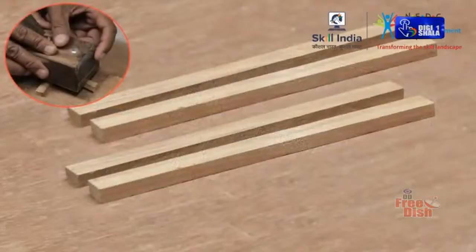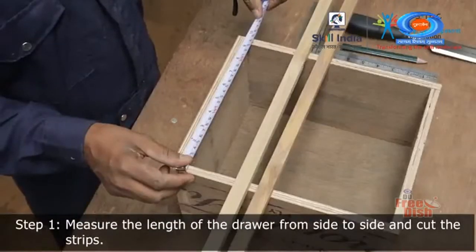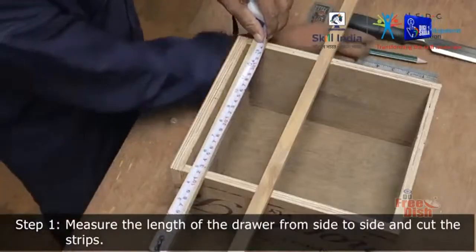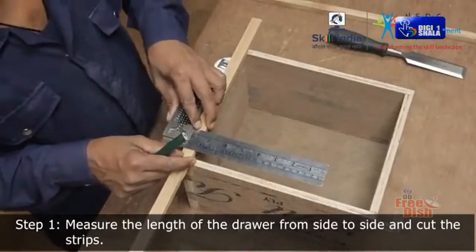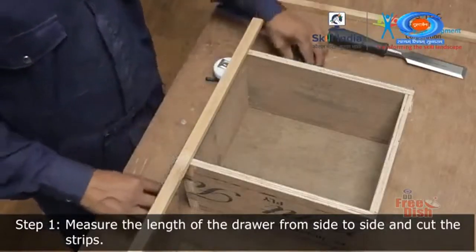Before you start, ensure the back side of your beading is smooth and even. If it is slightly uneven, use a smoothing plane to smoothen it. Using a measuring tape, measure the length of the drawer edge from side to side. Cut the strips to this measurement.